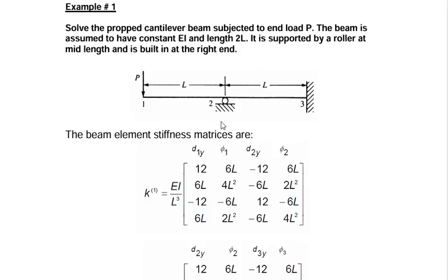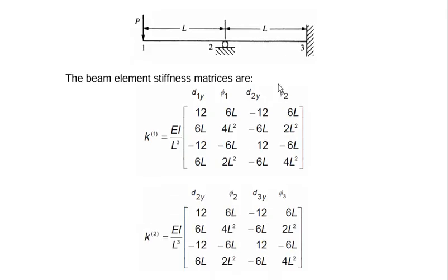In this case, the local axis and the global axis are the same because the elements are along the x direction. So we don't need to consider the element stiffness matrix for the arbitrarily oriented element. Rather, in terms of the local coordinate axis, we can consider the element stiffness matrix. So that's the 4 by 4 matrix in this form.